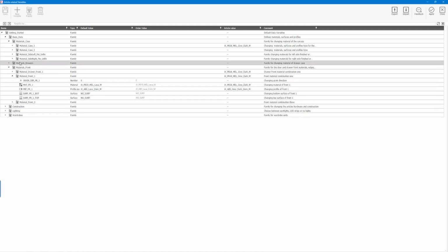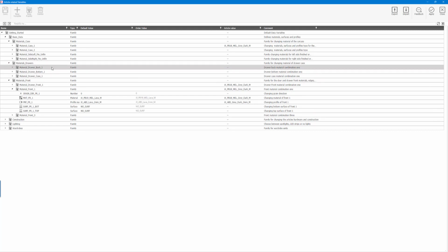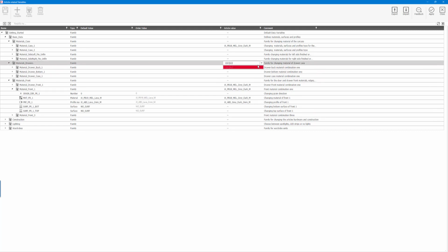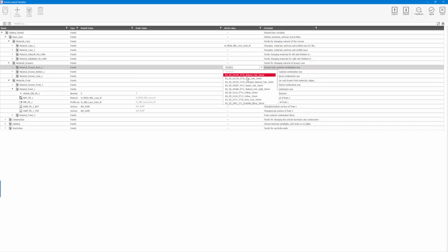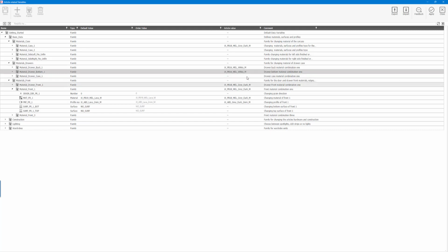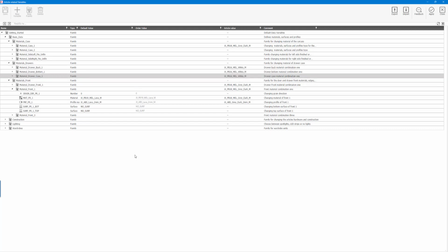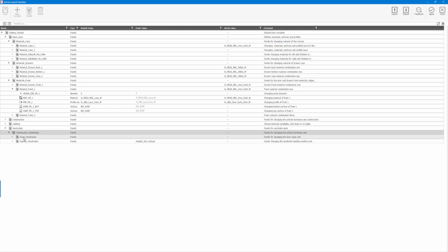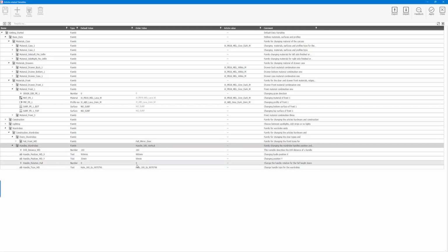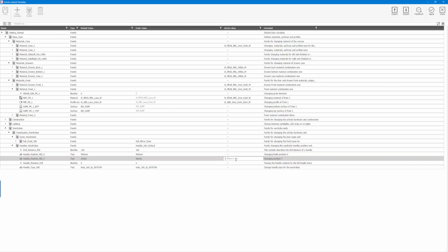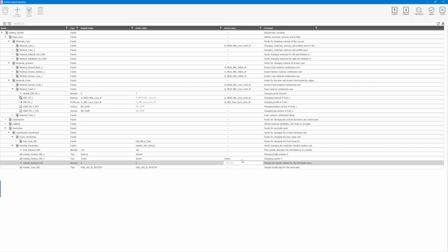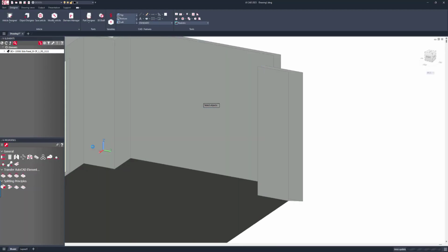And then in here for my drawer box material, I think what we can do is add in a similar material, or maybe we should go with something white, I think would probably help lighten up the inside for my drawer boxes. And then I also want the doors set with the handles, and I'll move these in and say that these should be 30mm in from the edge. Let's click apply on that and have a look.